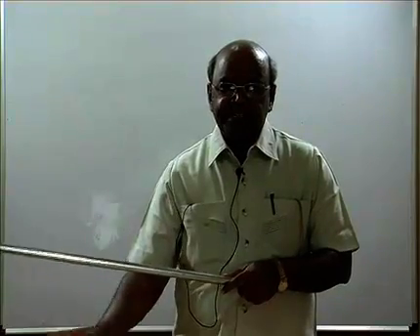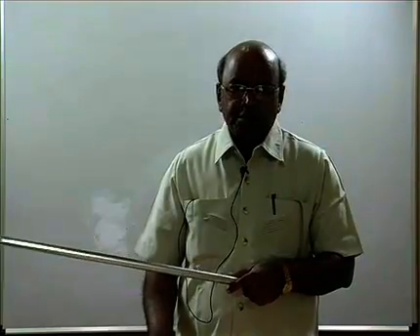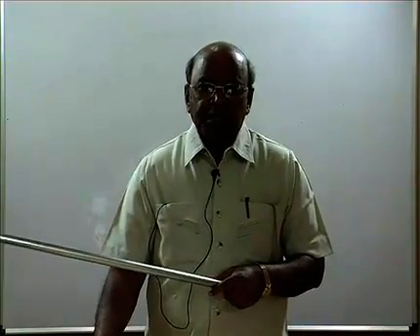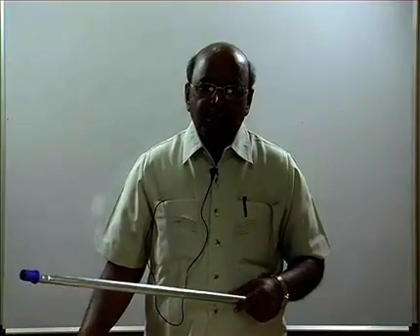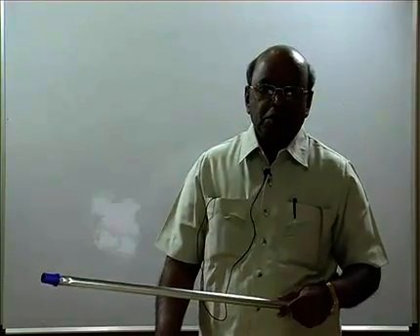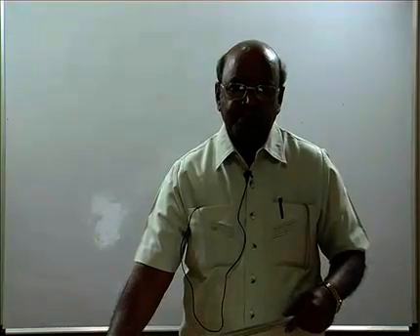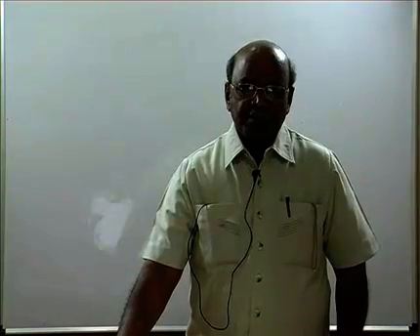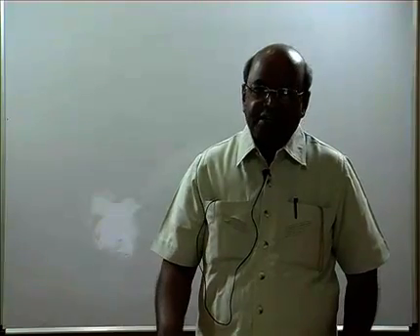So I am splitting the given problem into three cases: parallel to both, inclined to one, and parallel to the other. Now you can see in this figure, all three cases are done on a common XY line. Previously we have seen them on different XY lines, done separately. All the three cases you can do at one place on a common XY line by naming differently.